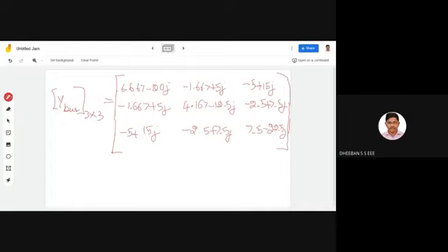Another part is that when you're moving towards your second unit and load flow analysis, it is mandatory to form this Y bus. So you just keep on practicing. Upon seeing the bus impedance value itself, you have to form your Y bus matrix.